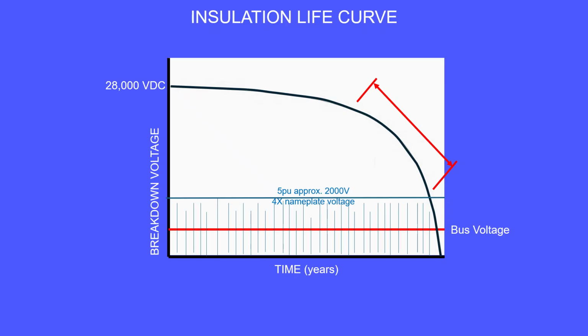What voltage did it start to turn nonlinear? Below full test voltage is worse than at full test voltage. A slope that turns nonlinear at 1000 volts is closer to the failure point than if the slope turns nonlinear at 2000 volts. And finally, did the motor trip on overcurrent or arc detect? If so, the motor dielectric is below the test voltage threshold.